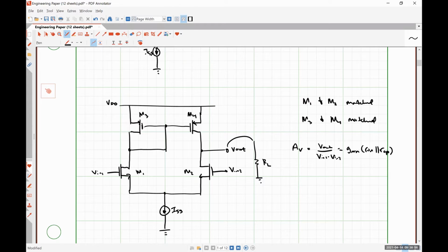It is the input stage of most real op amps. So we start there and then build on top of it to increase the gain to really large levels. Because we know the open loop gain for an op amp should typically be somewhere around a couple of 100,000, and best case scenario, we're going to get maybe 1,000 out of this guy. So we've got to bump up the stages and all that kind of stuff later on. But this is an op amp.